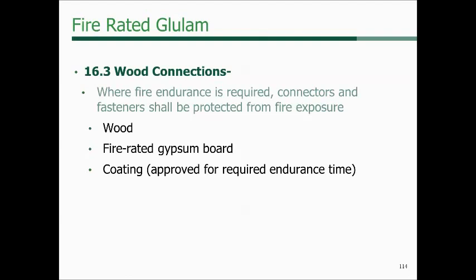But the one thing to consider also, which is key, is the protection of the connections when you are calculating an exposed member. The NDS specifies that if there are connections that are exposed, they need to be protected by either wood, gypsum board, or coatings, and this is key, the coatings need to be approved for the required fire resistance time or endurance time. In other words, if you're calculating for 1 hour of fire resistance, then the coating needs to have an endurance of 1 hour of fire resistance, 2 hours, etc.